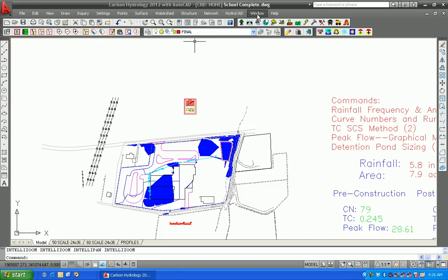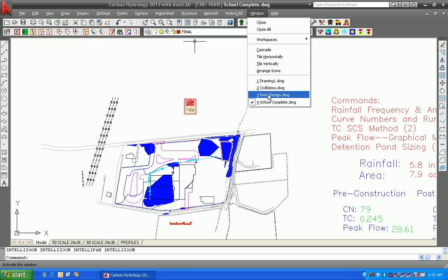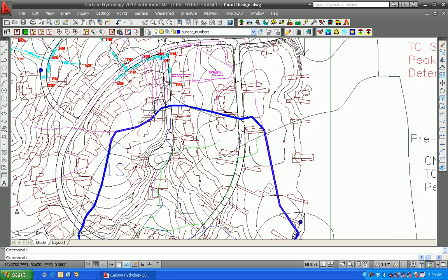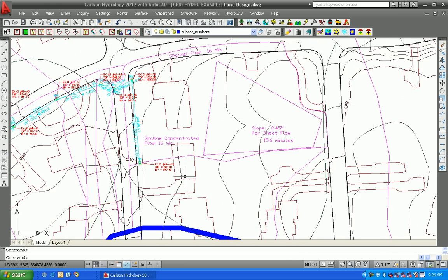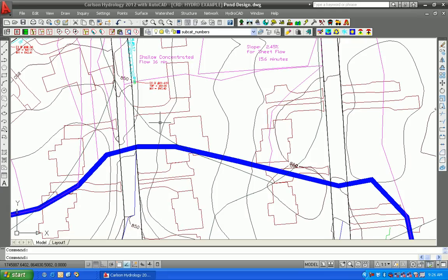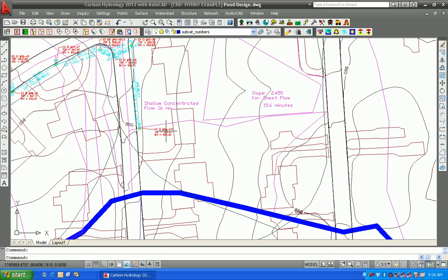But we would point out that where you have a file that involves a site where you want to get drainage into low points, but your DTM maybe is not accurate enough to reveal the precision you're looking for, in this case, we highly recommend that you literally draw the perimeters feeding into your inlets for storm sewer design.